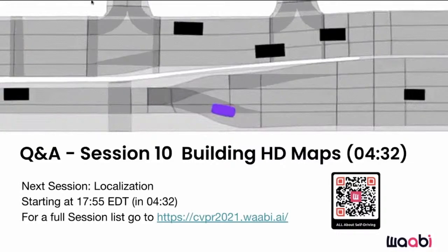Yeah, sure, Siva. Can you hear me okay? Yep. Awesome. Yeah, that's a great question, and it's a challenging part of mapping. So that can be done. There's many ways in which you can reference these things. In practice, you can definitely use these beacons, but an alternative is essentially just incorporating GPS data, WGS 84 coordinates, latitude, longitude into the SLAM optimization problem, such that you have this geo-referenced information basically everywhere in your map. And then you can cross-reference this, for example, for navigation purposes.